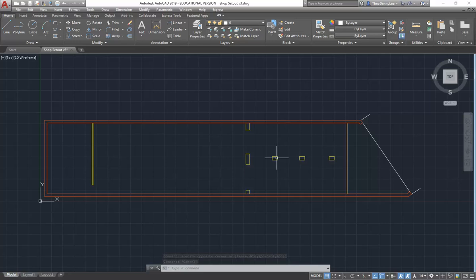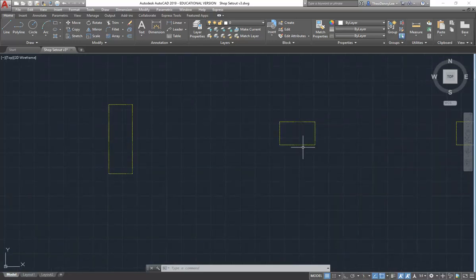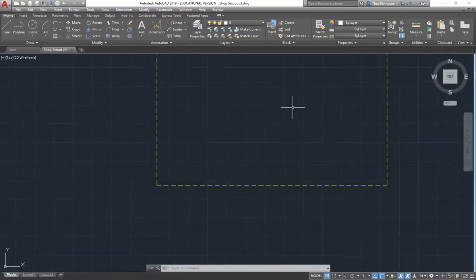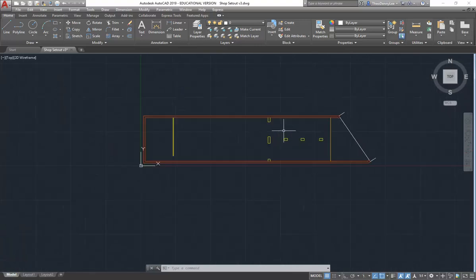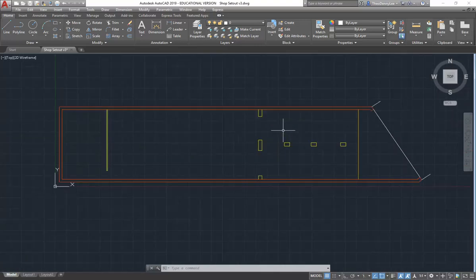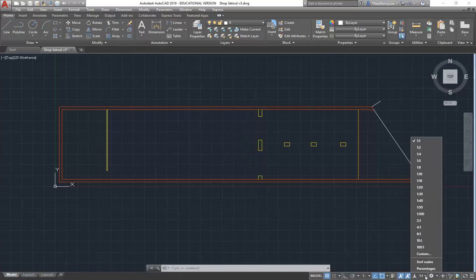But then what about the line type, the dashed lines? When I zoom right in, you can see they are dashed, but they're the wrong size. And that's where people have the most problems with line type in AutoCAD, and other CAD programs are the same, because they have scale. The scale can vary a lot. So you need to think about the scale when you look at things like a dashed line.